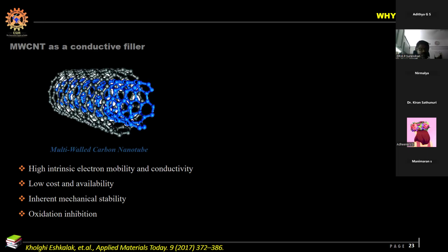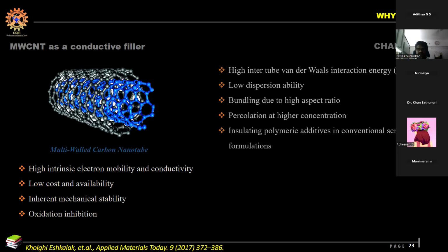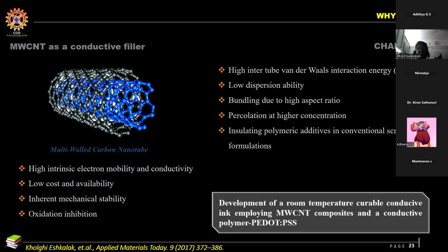We made the sensor with multi-walled carbon nanotubes, but they do not have sufficient electrical conductivity, because the inter-tube resistance of multi-walled carbon nanotubes is very high, and they have a very big effect of bundling. So we would have to spend a lot of hours debundling them.